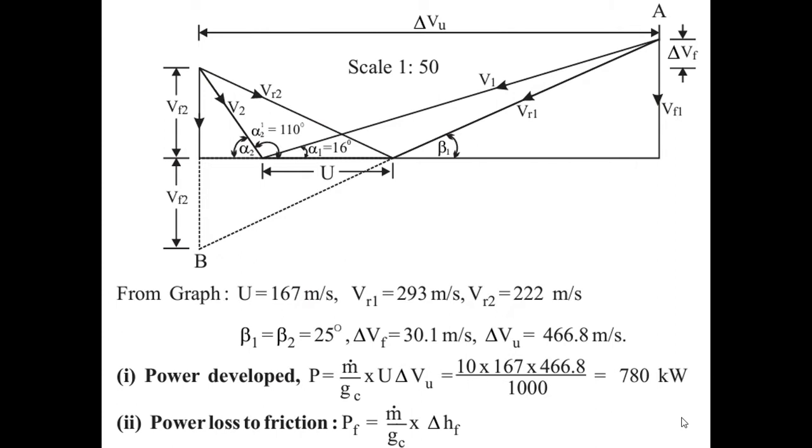And delta VF, sir? Delta VF. VF1 you know from the graph. VF1 minus VF2, if you take, you will get delta VF. Okay, sir. If it is a turbine, if it is a pump or compressor, because the question comes for students, it may be VF2 minus VF1 also. Yes, it is for pumps and compressors, power absorbing machines. In that case the delta VF value will be same, but the difference will be VF2 minus VF1. In turbines, VF1 minus VF2 will be delta VF. Okay?